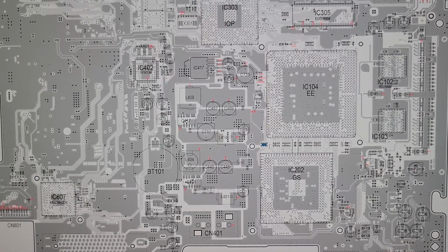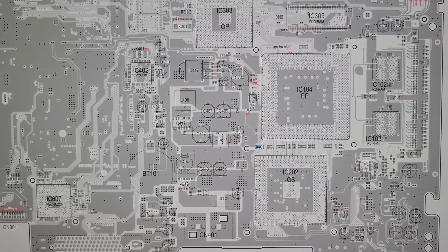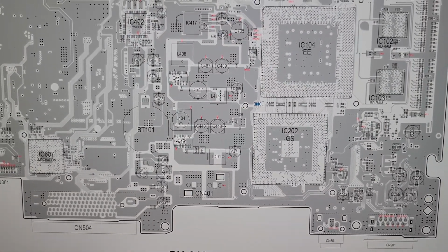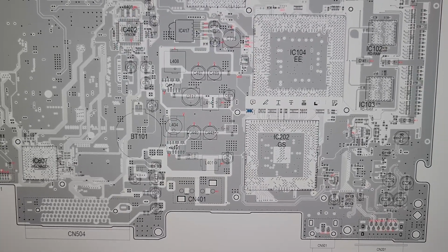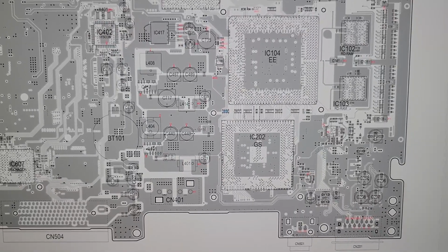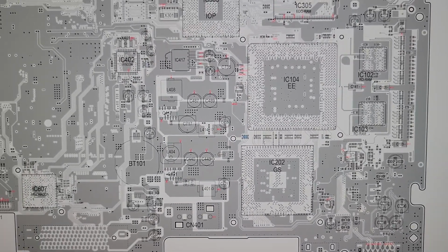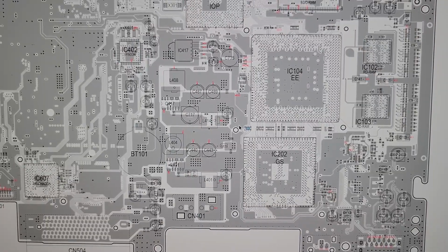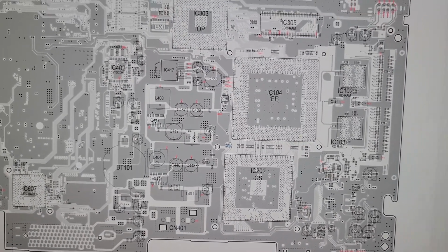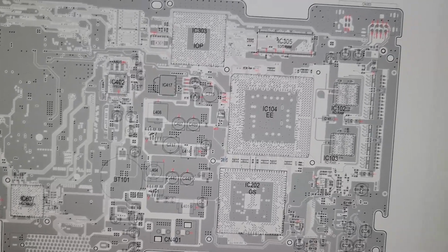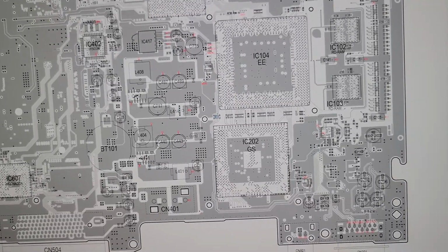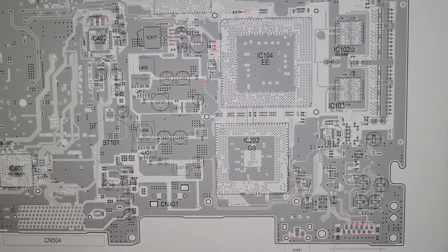You gotta have a diagram, folks. You gotta take them off a donor board. I guarantee you I could probably buy a bunch of PlayStations with distorted video now and everything else, and it's gonna be one of these top resistors on the top that go bad. You just gotta use an ohm meter and ohm them out. It doesn't take no more than 5. It takes more time to take the thing apart and to get it off a donor board than it is to basically fix the issue here.